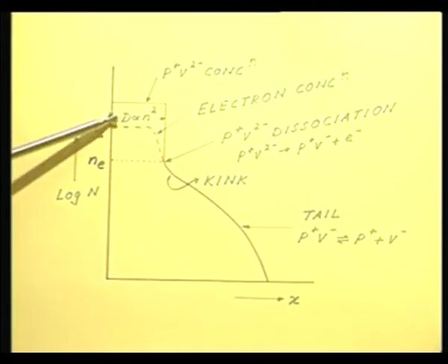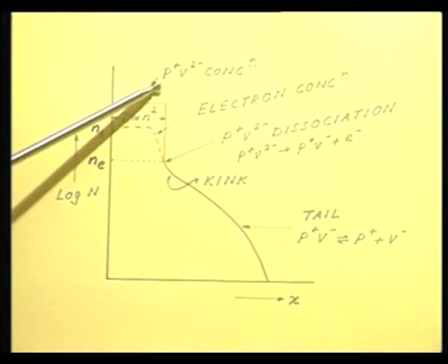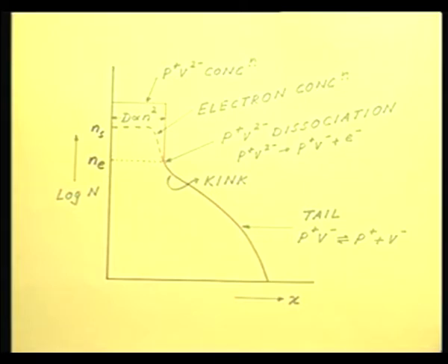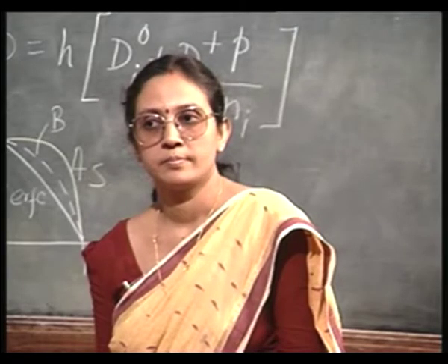Over this depth there is hardly going to be a change from the surface concentration, it is going to be truly box like, and then it starts to fall abruptly, very steeply, right. As the dopant concentration starts to fall very steeply, the position of the Fermi level changes, right.